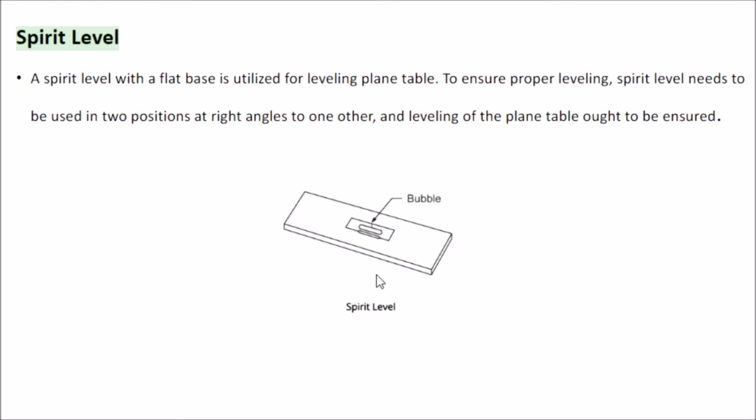Spirit level. A spirit level with a flat base is utilized for leveling the plane table. To ensure proper leveling, the spirit level needs to be used in two positions at right angles to one another, and leveling of the plane table ought to be ensured.